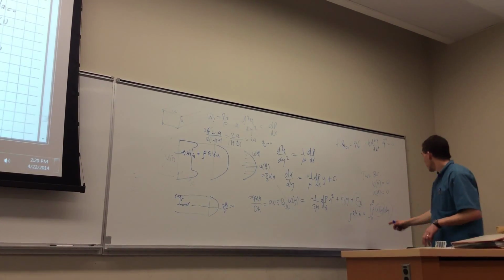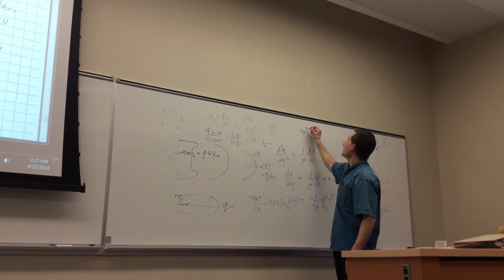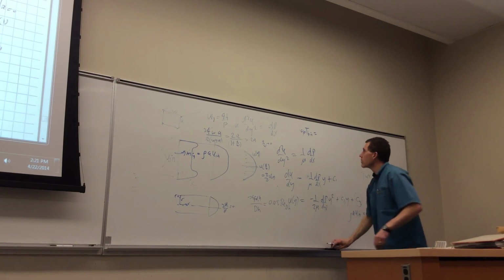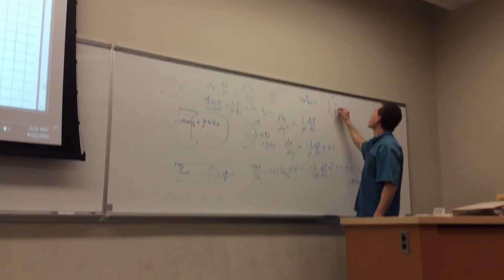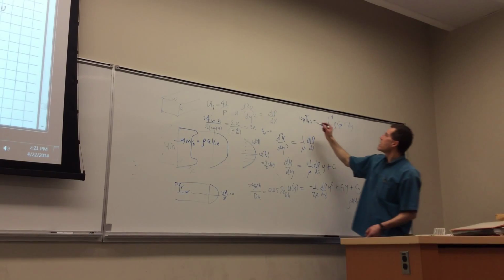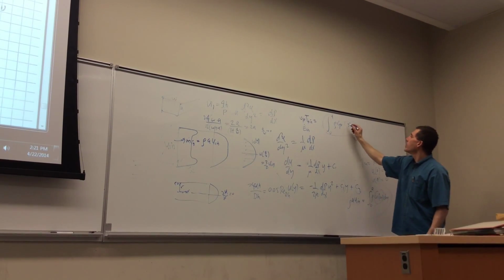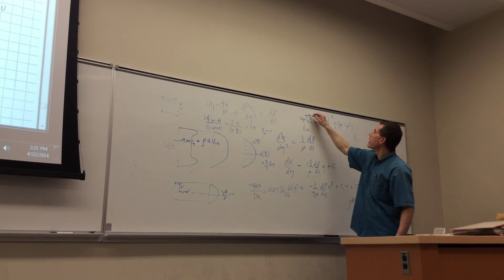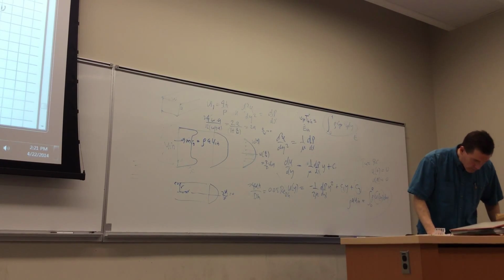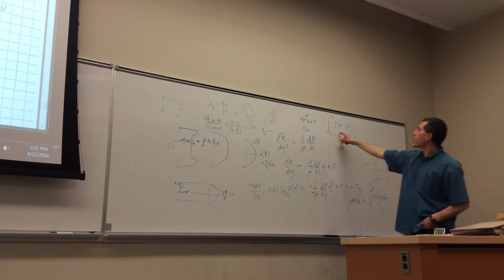So for that equation, you'll find the mean velocity. What about the temperature? What equation would you use? Well, m dot Cp T bulk in would be what? That's the energy in, so it would be the integral from 0 to A of rho Cp T dy. This is E dot in, and this is E dot at whatever location you know your T of y. So you can get a bulk temperature from that. Did they ask for that bulk temperature too? Yeah, okay. Same procedure, except this one was with energy, and that one's just mass.